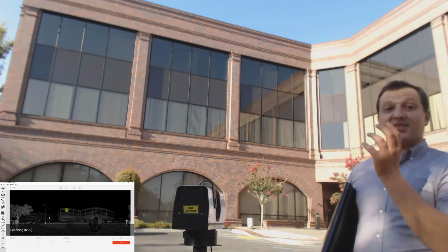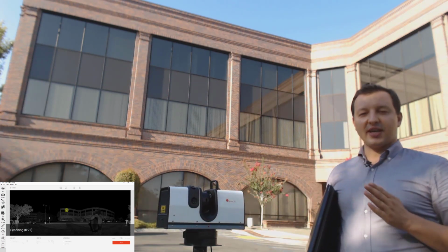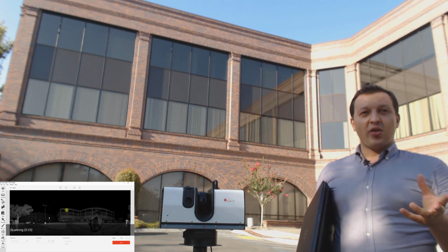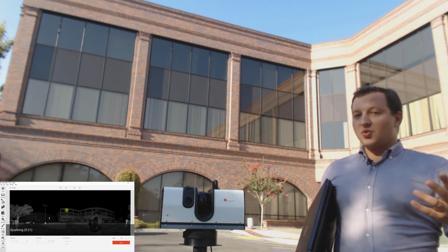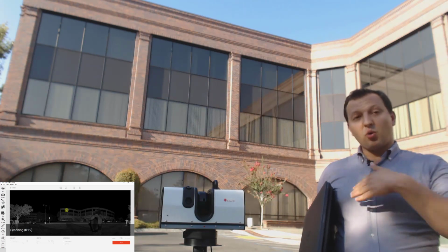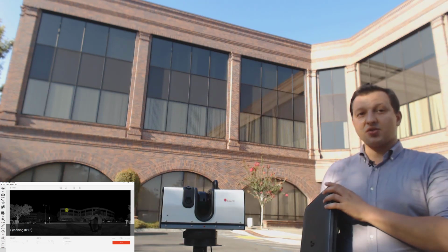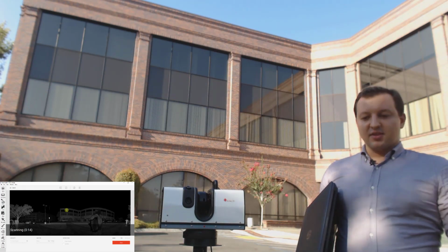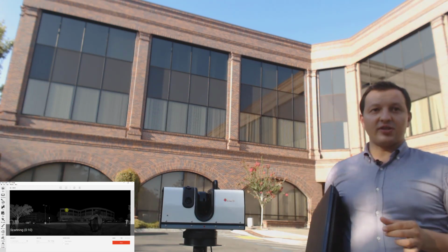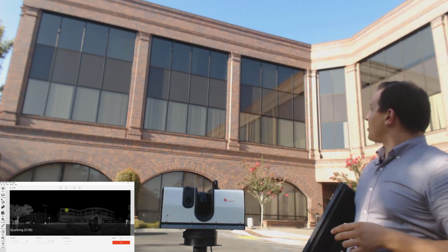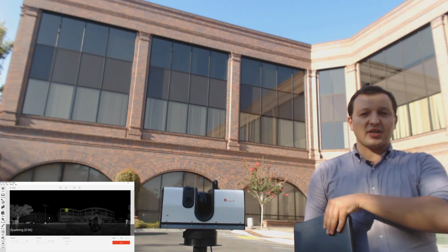The reason why we're not going to scan the entire environment is because if we scan at full resolution, at the best the device can do, at the maximum point density, then it's going to take us just over 30 minutes to complete the 360-degree scan. And if we do a 360-degree scan with a lower point density, which we can actually set in the software, then we're going to get less resolution. So by limiting to just one sliver of the data, just a few arcs a degree, we're going to be able to complete the scan quicker and in higher resolution.